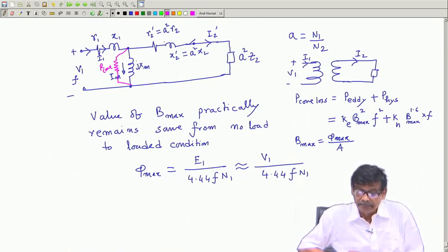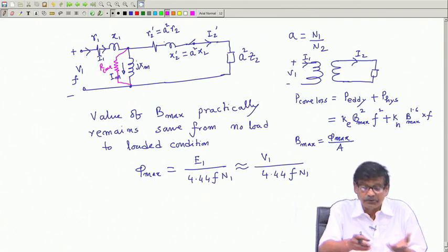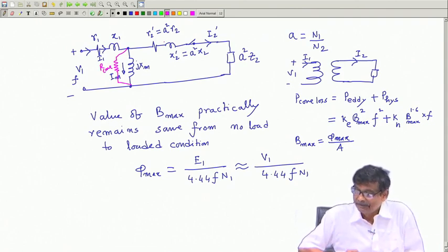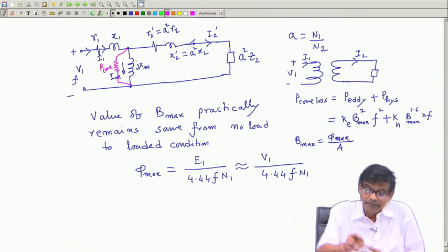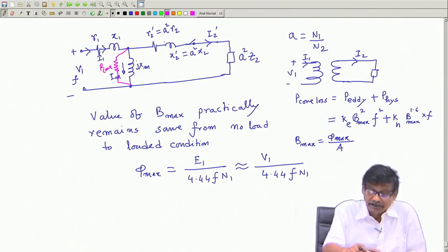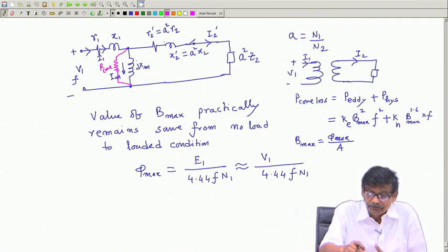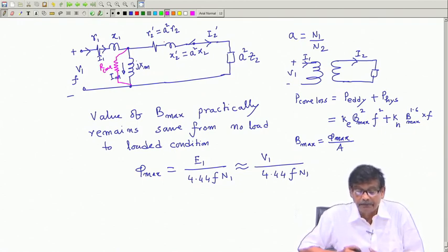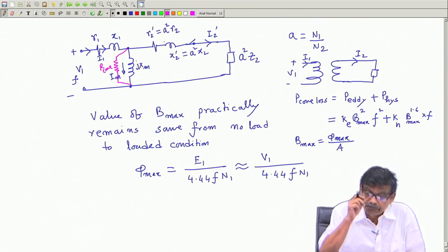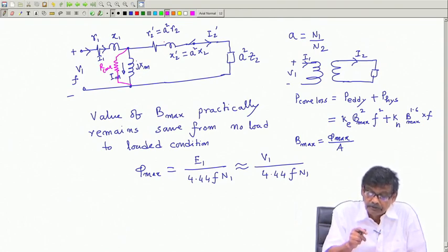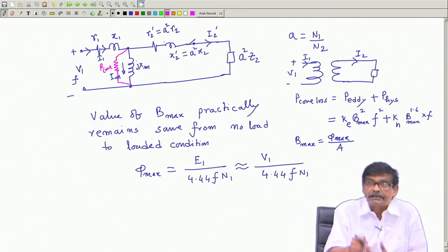And it certainly should not be in series, because it depends on Bmax, and Bmax is decided by this voltage across this impedance, Im, that decides Bmax. Therefore, the core loss resistance, which will represent core loss, must be shown connected in parallel with Xm.